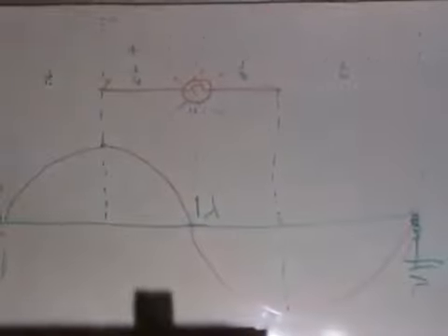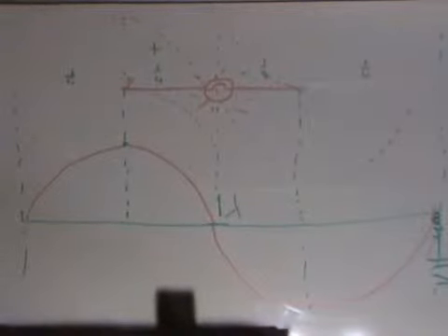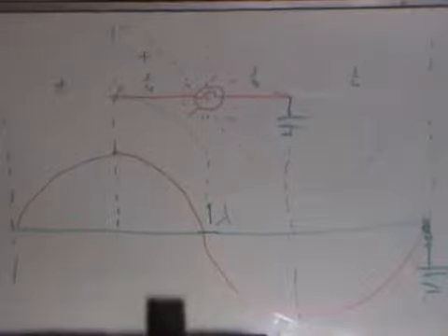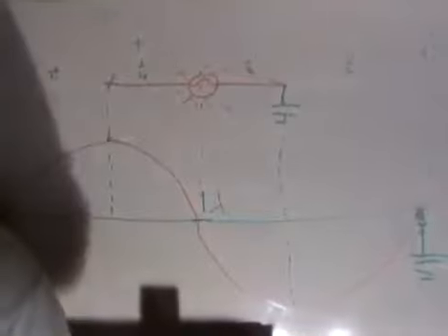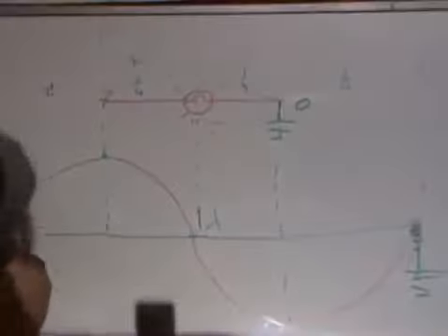The ground acts as the other half of the dipole and could be due to ground conductivity, also referred to as ground wave transmission. Radio transmissions in the low to medium frequency bands ranging from 30 to 3000 kHz are particularly reliant on good ground conductivity, as their primary propagation is by surface waves.